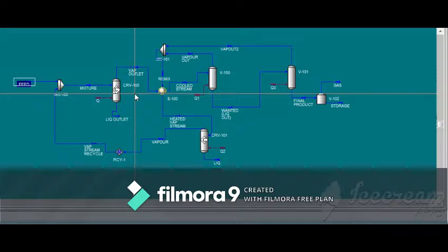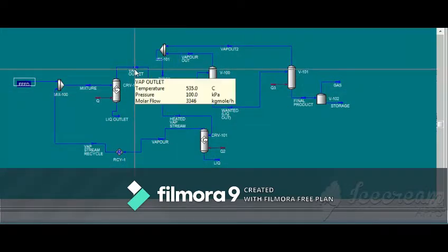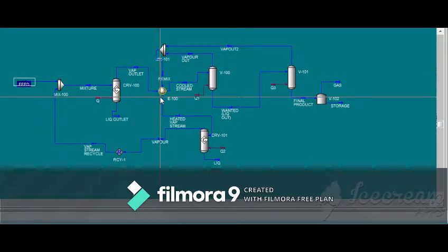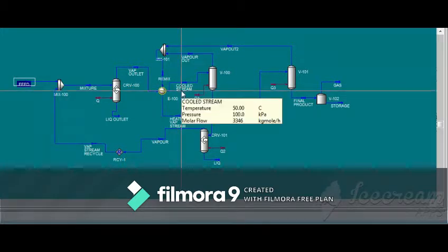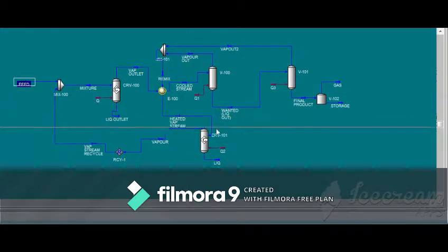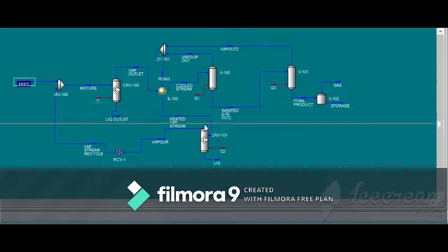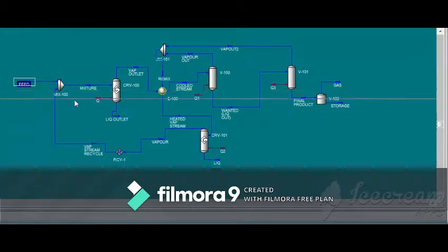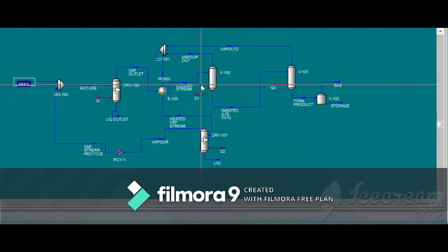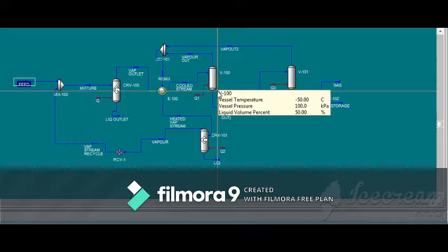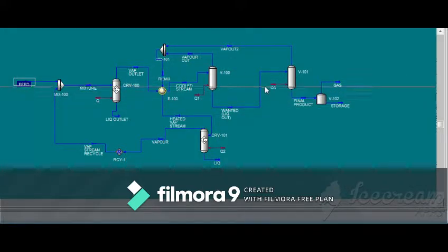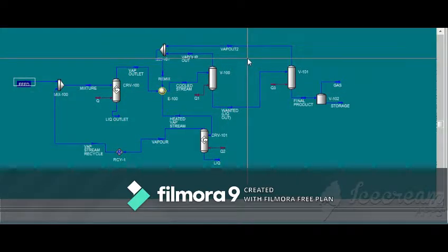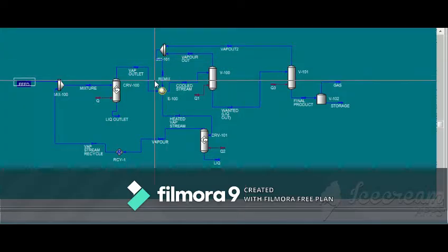So in order to separate products and reactants, a heat exchanger is needed. The product then enters the heat exchanger, where it produces two streams, a cold stream and a hot stream. The hot stream enters the second conversion reactor, where the products enter the mixer for recycle. Then the cold stream enters the liquid vapor separator, and the product then enters the final letdown separator. Both of the top streams of the separators are combined and go back into the heat exchanger.